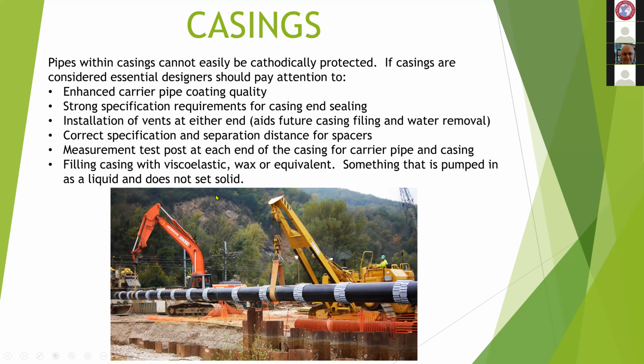But some things that you can do is make sure that you properly calculate the separation distance for the spacers, because you need to look at the load of the pipe and the weight of the pipe when it's got the product in it, and make sure that the spacers are at the right distance to avoid unacceptable sag and still maintain the separation. A test post at each end of the casing is very helpful for us.